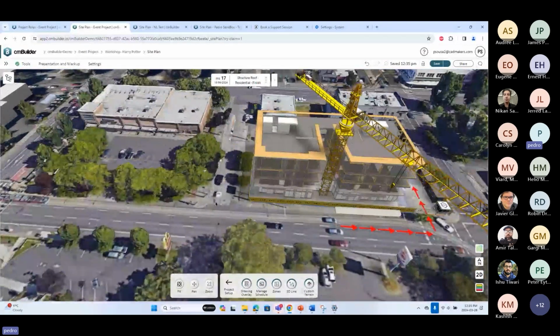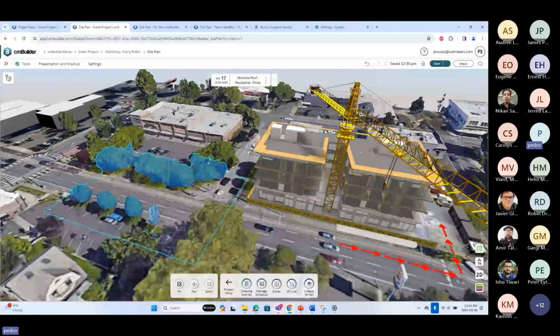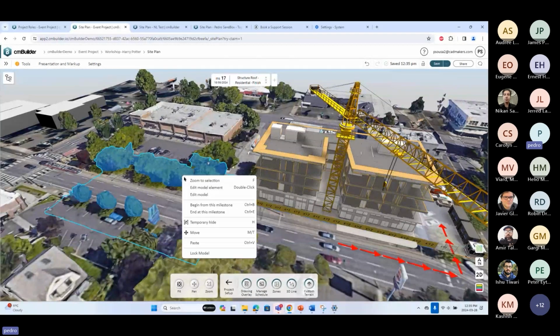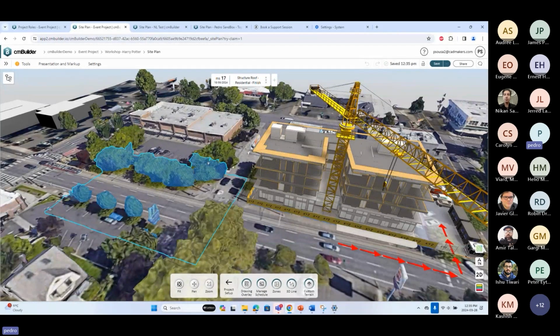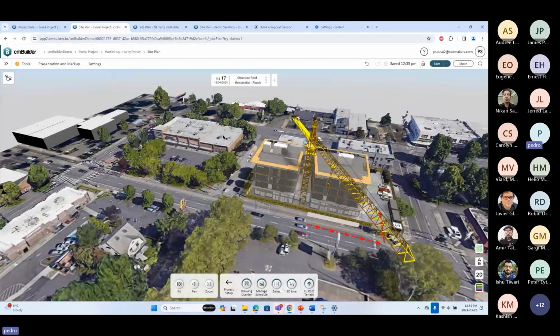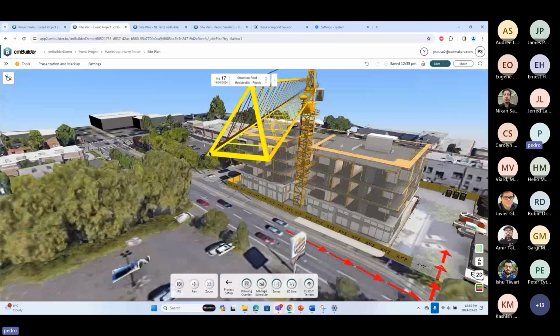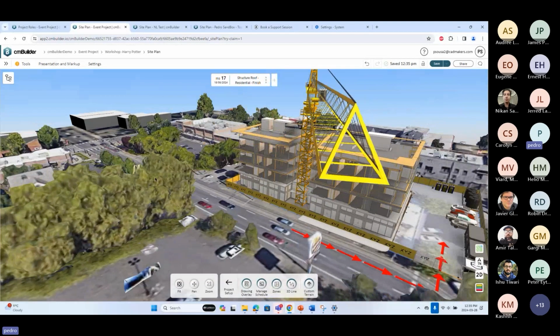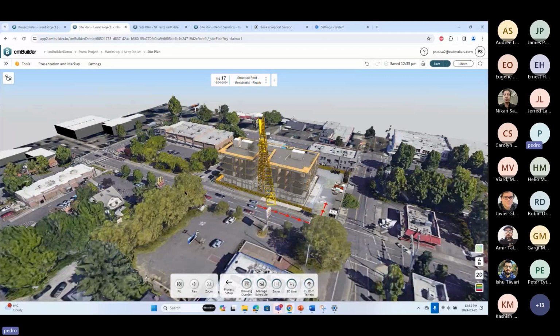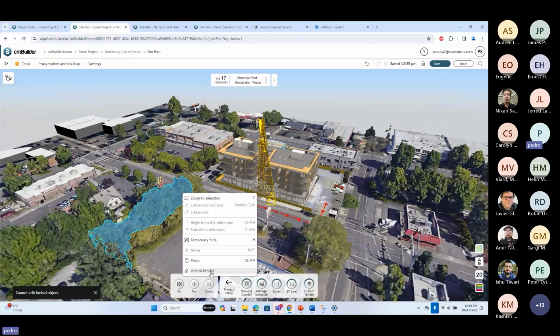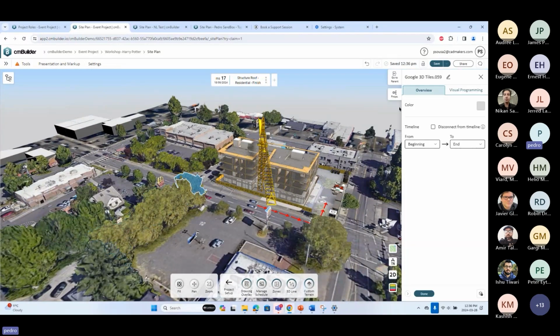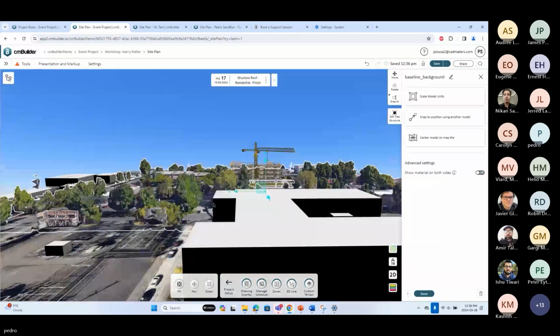That's the idea. You can also do the same for imported models. So if you select a part of your imported model and you lock it, the whole model now will be locked. So I just selected one part, but this whole model of the surroundings is now locked. And if I double click, I'll be able to select them. But if I click once, I can't select that object anymore. I'm clicking once over here right now. Okay, so to unlock these objects, again, you can double click and then unlock the model. And now you're ready to start working with it again.